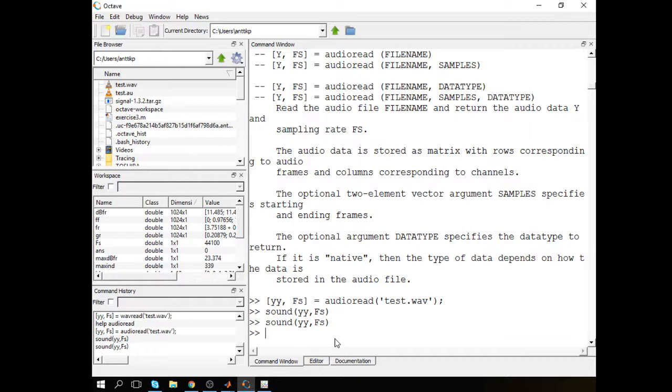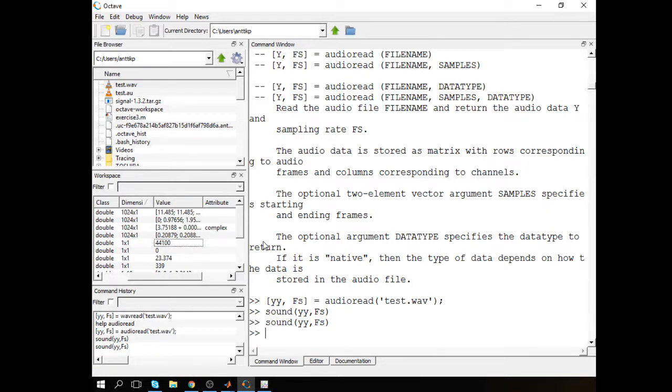So, the frequency analysis of the signal. That was about 1 second long, and what is my Fs? 44.1 kilohertz sampling rate. So it's CD quality audio of a ping. So what I can do is, for example, do the old school fast Fourier transform of one section of the data.